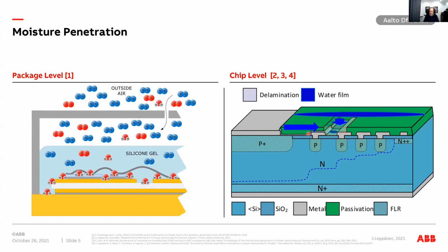And then on the other hand, as I described in the first slide, there can be a nitride layer on top of these metal guard rings beneath the polymer type passivation and the metallization, and that can obviously also corrode when moisture has penetrated the passivation, and then there will be a loss of adhesion, for example, and you can have a path for the moisture to transport through here towards the area between these guard rings.